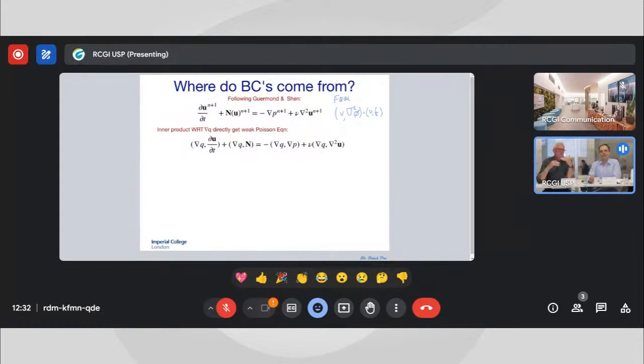And then I'll apply the divergence theorem or integration by parts, and we'd normally end up with my Laplacian operator looking something like the gradient of v in a product with the gradient of phi is equal to, plus a boundary term. So I'm going to introduce some angle brackets, v, grad phi dot n is equal to v comma f. I'm going to go through that step in a bit more detail in a moment. We've not seen it before, but that's just kind of a reminder. If you have a finite volume method, those are the steps that would take place.